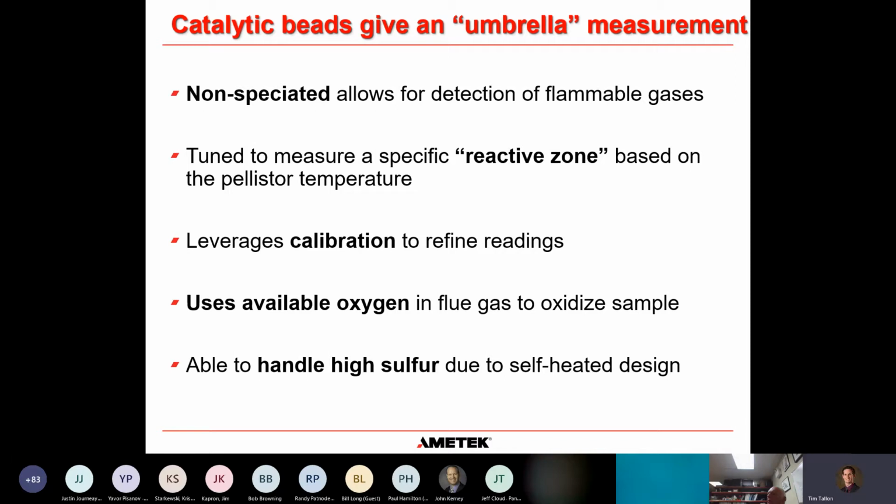And we use calibration to refine the readings and to zero in on those two different elements to refine the readings. And what happens is the combustion reaction is completed by having gas oxidize the sample on the surface. So whenever a measurement's taken, the flue gas has additional oxygen in it, and that available oxygen in the flue gas reacts with the methane to oxidize the sample on the surface of the catalytic bead, and that's what's used to complete the reaction.